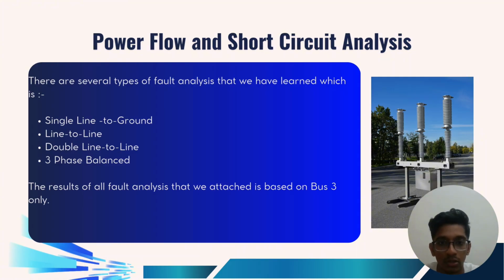So I will explain about power flow and short circuit analysis. There are several types of fault analysis that we have learned, which are single line to ground, line to line, double line to ground, and three phase balanced. The results of fault analysis that will be attached are based on bus 3 only.